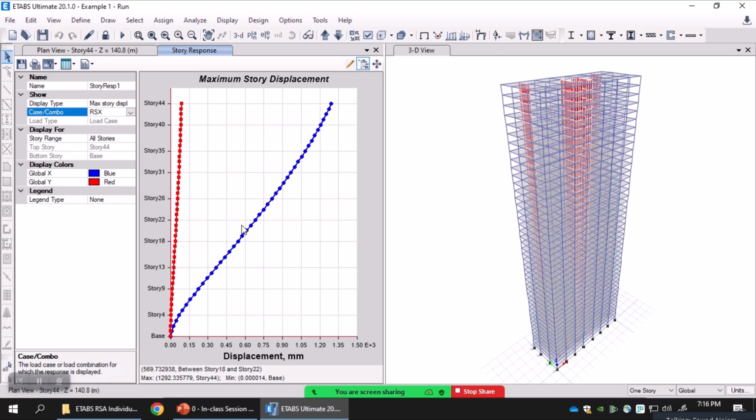The modal contributions will tell you which mode is contributing the most and which mode needs to be suppressed, and then looking at the mode shape along the height and the response of that particular mode shape, you can decide the optimum location of that particular damper or any control measure, and what frequency and time period it should be tuned to in order to optimally suppress the response.